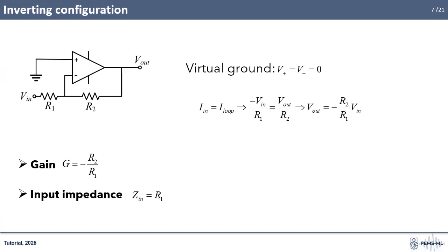On the other hand, in the inverting amplifier configuration, the input signal, Vin, is applied through a resistor, R1, to the inverting terminal, marked minus, while the non-inverting terminal is connected to ground. This grounding ensures that the reference point of the amplifier remains fixed, allowing the circuit to accurately process signals fed through the inverting side. The output signal is routed back to the inverting input through resistor R2, creating a feedback path that stabilizes and defines the gain of the amplifier.